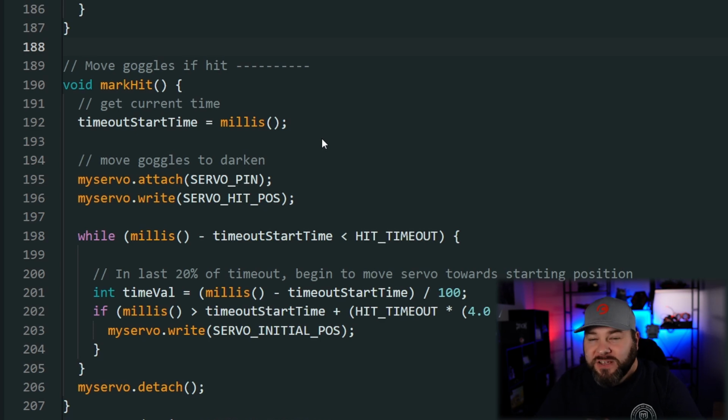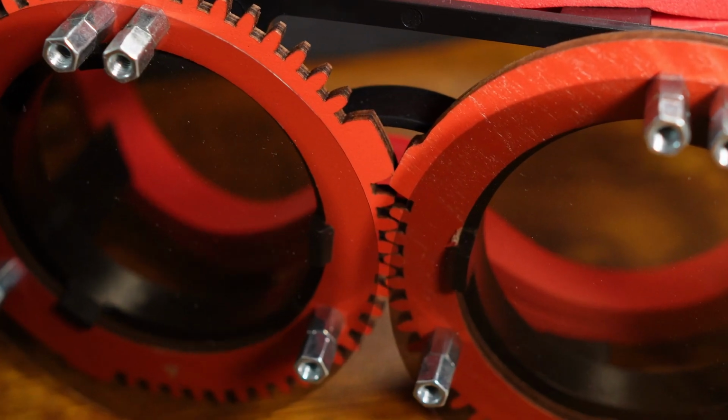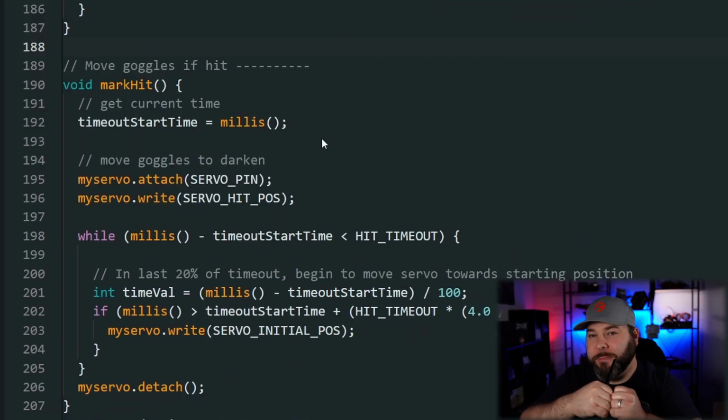But that complicates things for the servo movement because it's moving a certain amount of time. Instead of having it stop at a time, it just hits the mechanical stops or the pinch points where they run into each other at the end, and it should stop it. But we have seen some issues with it not working the right way. This is where you can modify the code so it will actually stop the servo from trying to move when you set it to 90, which is the stop, or basically the middle ground. 0 is max one way and 180 is max the other way, clockwise or counterclockwise, and 90 is the middle ground where it doesn't move the servo, it doesn't give it a speed to move to.